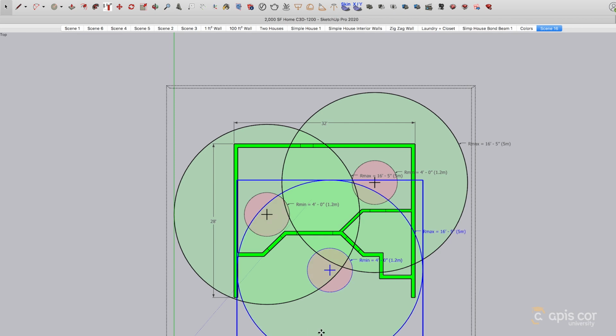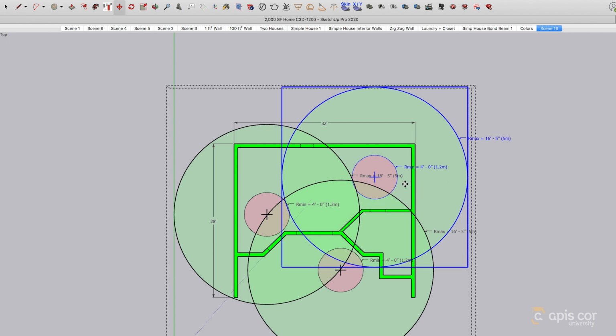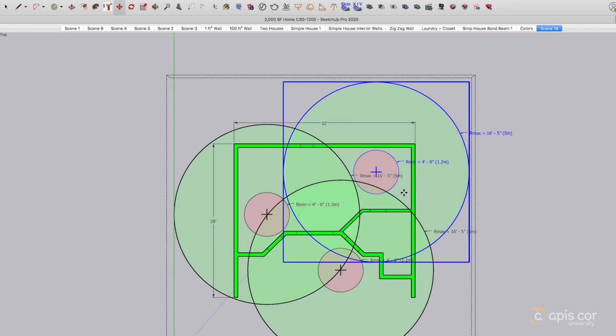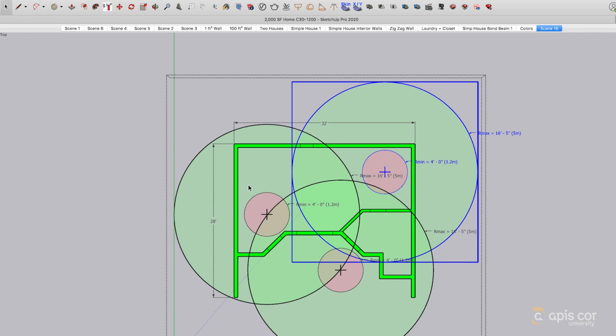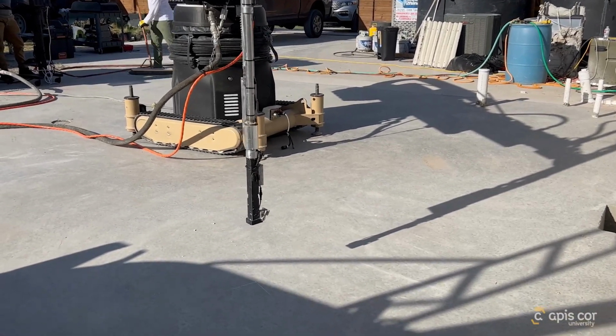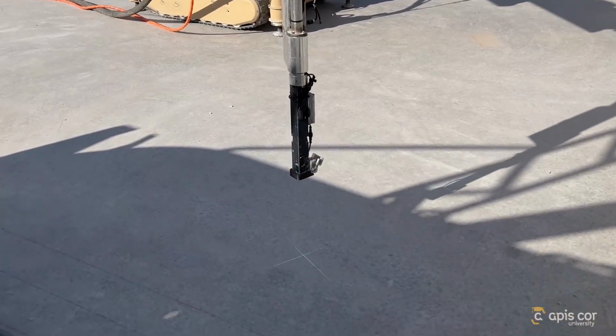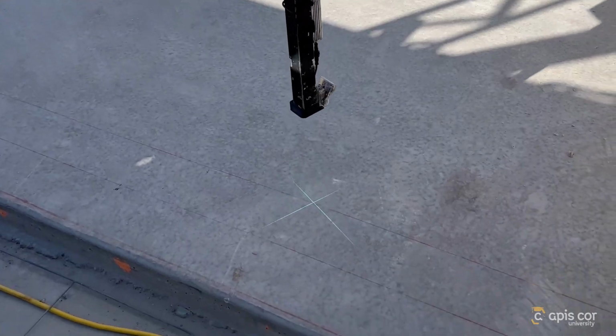In fact, the printer operators can technically position the printer in any location, as long as the wall section's toolpath is within the printable area, and the printer can move freely without hitting any obstacles or obstructions. As we'll learn about more in a later section, this is because part of the calibration procedure involves snapping the G-code to the slab, which is the process of digitally repositioning the toolpath in relation to the printer's current position. In essence, we adjust the position of the digital 3D model because this is faster and easier than trying to physically move the printer into the exact perfect location.